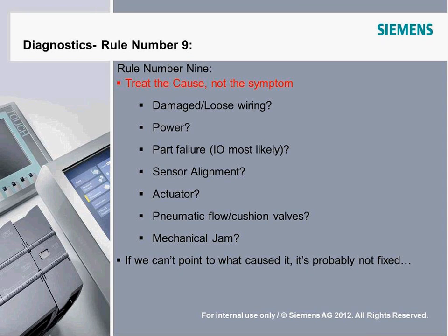Part failure. I mean, IO is the most likely. It is actually where it's going out where the rubber meets the road. If you have noise issues, if you have ground issues, if you have electrical discharge issues, then you can blow IO modules. Oftentimes, a lot of the machines that I was out in the field trying to fix were nothing more than just an alignment of a sensor. I mean, things mechanically go out of adjustment all the time, so don't forget about those things.